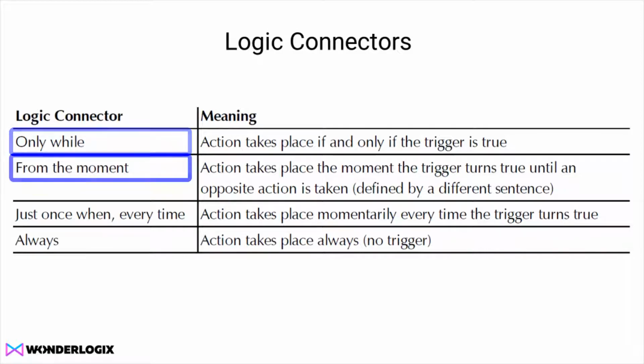If I say from the moment of, then in this case, this is where we have to set a condition and then clear a condition. So from the moment that I push a button, even if I let go of the button, I want something to occur. And then at some point, I want to be able to clear that. Maybe I have to push another button or cross another condition. Then I want to clear the action that has taken place. And then there'll be a resolver sentence that says, well, what if you receive both buttons, right? What if there's a start and a reset and someone presses both, or you have a short in the line, and so the system thinks that it's receiving both signals at the same time. You want to be able to say what to do if there's a conflict.